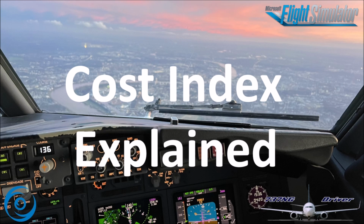That might be worth it when you are running close to a 3-hour delay, so if you are very short of paying compensation to the passengers, but that is pretty much the only situation, except for a night curfew where the destination airport would actually close, where it would make sense to increase your cost index. At least in my airline. Other airlines are seeing it very differently.